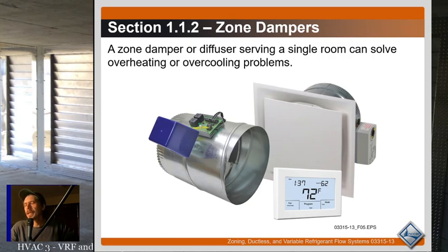emphasize this is that you don't want people to use zoning dampers, a zoning system, as a means of not cooling or heating unoccupied areas of the house. In other words, the goal of a zoning system isn't so that you can set all the bedrooms at 80 degrees during the summer since nobody's in their bedroom, because you're usually going to waste more energy overcoming that heat difference between different spaces of the house than you are going to save energy by not cooling or heating certain portions of the house. So in other words, on a zoning system, pretty much all the thermostats should be set close to the same temperature, within a couple degrees.